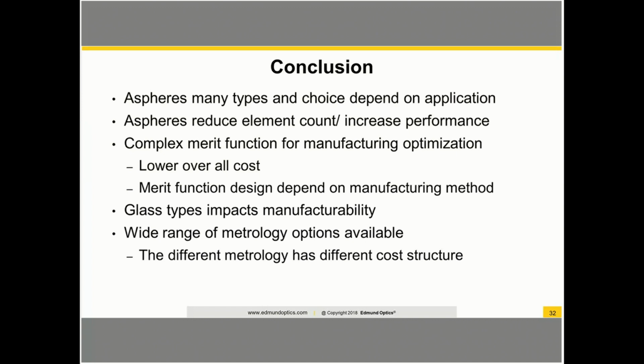Sure. So in our factory, we have a set of standard metrology that we generally use for grinding and polishing. It can generally measure up to about a 50-degree slope. This isn't a hard limit though, because we do have other pieces of metrology that don't have any problem measuring a full hemisphere out to a 90-degree slope. There also might be some challenges to consider for coating these lenses, but those coating limits probably won't be that different than what you would expect from a spherical lens.